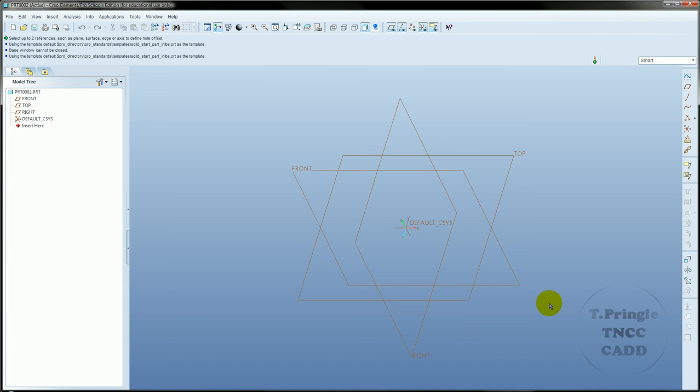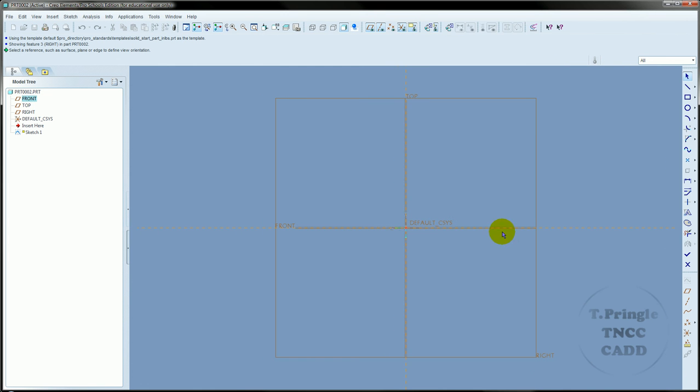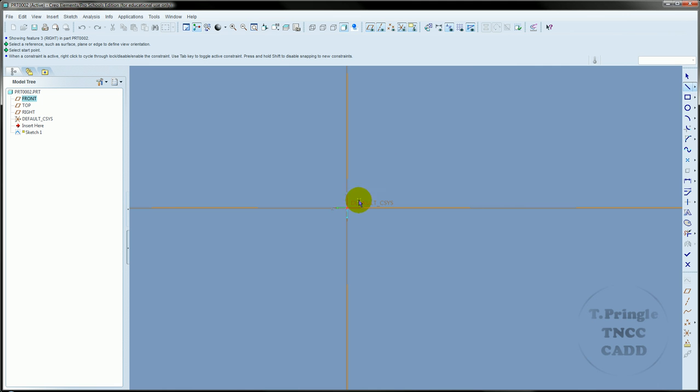For exercise 151-68, I'm going to start this one on the right side. Now, I know that I'm going to be using the revolve command to do this, but I also know that the object is completely symmetrical. So I'm going to take this one a step further, and instead of just using the revolve command, I'm also going to incorporate the mirror command into this particular object. That way I can create even less work for myself.